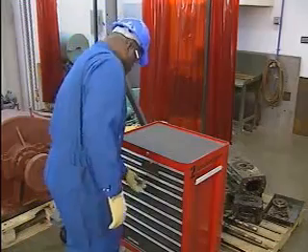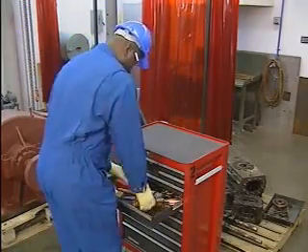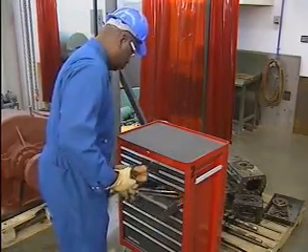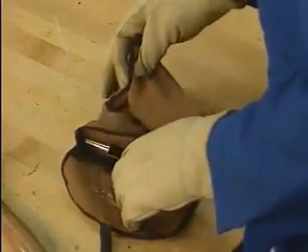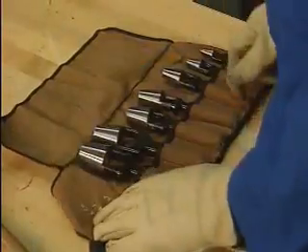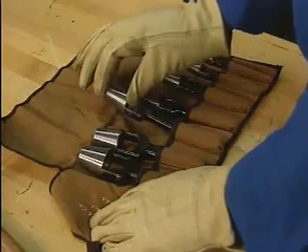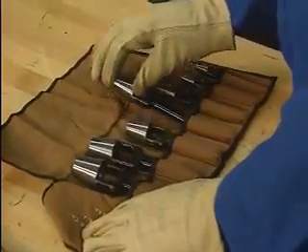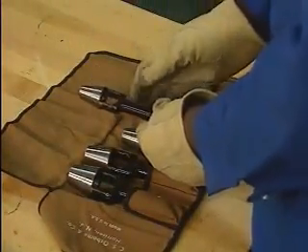When he's finished cutting the gasket to the desired shape, the mechanic uses a hole punch to make bolt holes in the gasket. A hole punch is the best tool for this step because it cuts a clean, precise hole. Well-formed bolt holes are important because they allow connecting bolts to thread easily through the gasket material to avoid tearing or buckling.